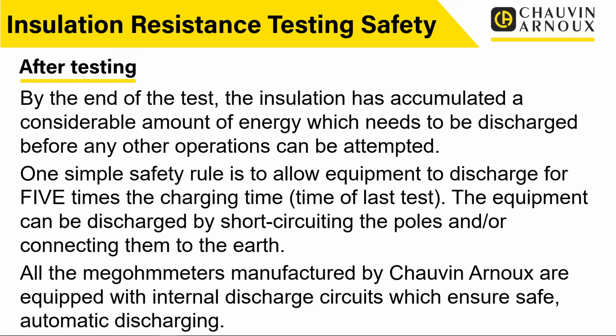So if you're moving from point to point to point carrying out that test, those items that you've touched potentially are still charged up until you discharge them. It'll only discharge when you finally stop the test button and stop the test. It'll discharge whatever it's connected to. So again, think about that.